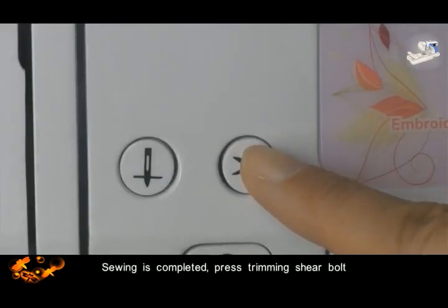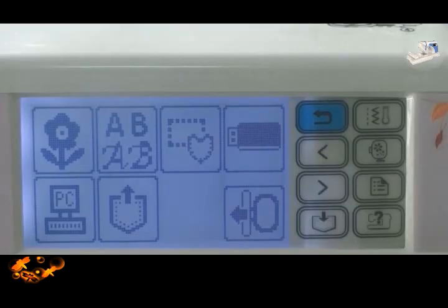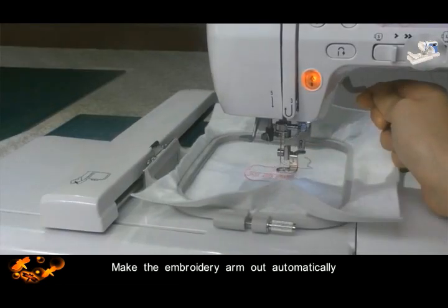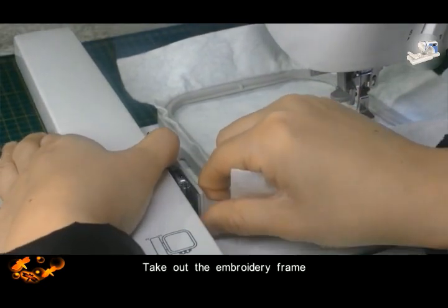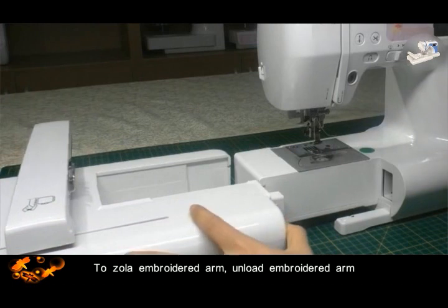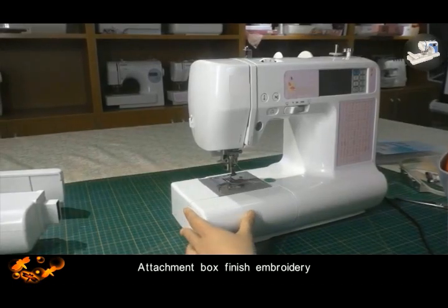Sewing is completed, press the trimming shear button. After the completion, press the dotted box out key, lift the presser foot, and the embroidery arm will come out automatically. Take out the embroidery frame. Hold the bottom of the handle, and unload the embroidery arm. Attach the box to finish embroidery.